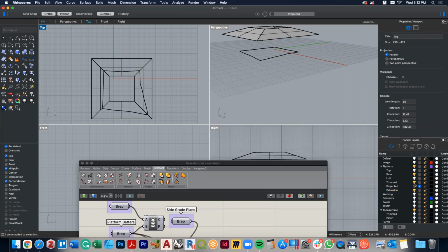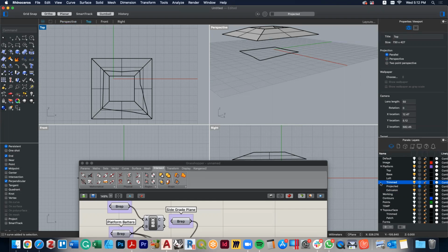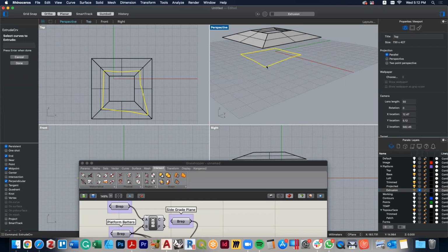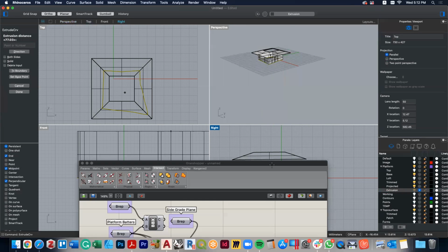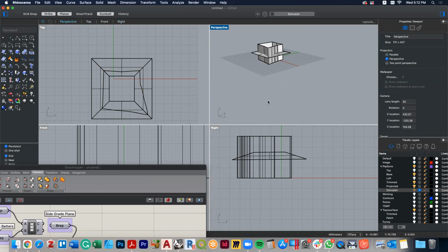Right, and so if we've got trimmed, this is where we've got loft. So we're now going to trimmed. We turn trimmed on, and then I'm going to make extrusion current, and I'm now going to extrude, not curve taper, just extrude. I'm going to extrude this one up, and I'm now going to move it through there.